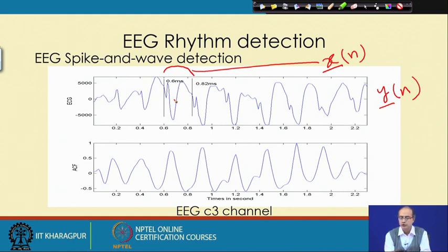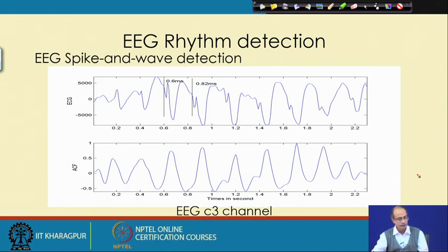In fact, visually also if we look, spike and wave is repeated in the range of about 0.4 to 1.8 or 2 seconds. Within that range, many times it is getting repeated. Now, because we have taken the autocorrelation coefficient, it is normalized between -1 and 1. So, we can quantify that also and have a quantitative decision based on these findings.